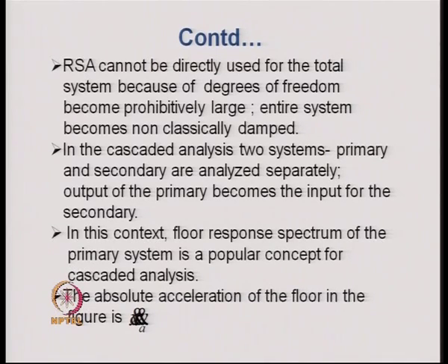So, first the floor response spectrum is obtained from that time history, and once we get the response spectrum for the absolute acceleration time history, that response spectrum is input at the base of the piping system, and we carry out the usual response spectrum method of analysis that we have discussed.